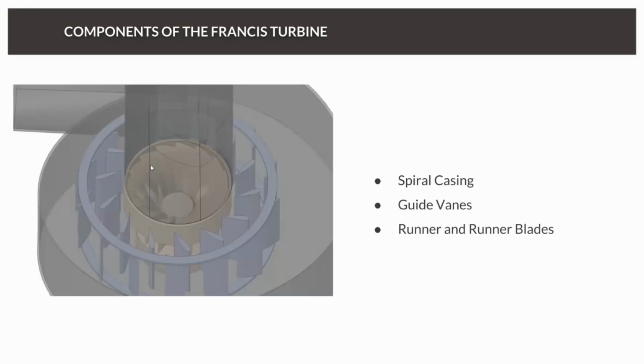And just to take a little bit of a look inside too, this gives you an idea of the flow. You can see it would come along the top and pass clockwise through the structure. The bluish vanes are relatively static, so they're essentially the stator, but they can move on their axes. In our analysis, we haven't done that because we've gone with a fixed flow rate, but they would change and move based on the flow speeds moving through the model. That's important because we obviously want the most optimum energy extraction from the water.